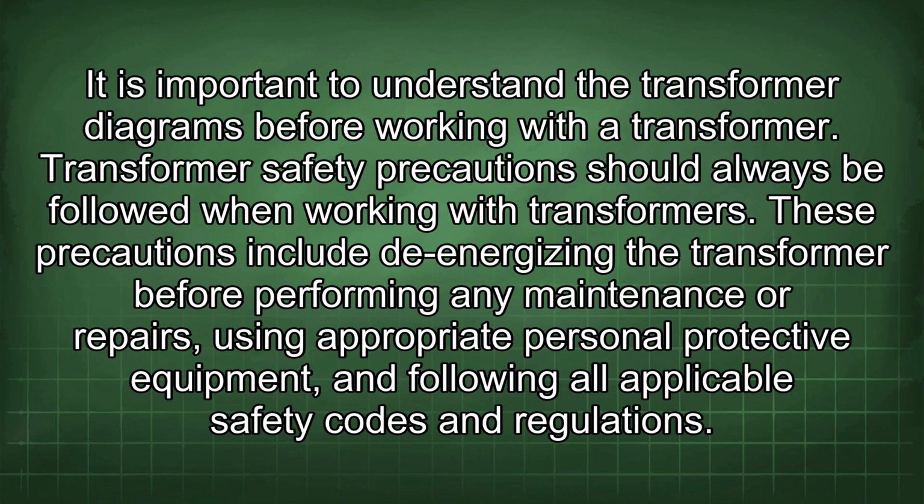Transformer safety precautions should always be followed when working with transformers. These precautions include de-energizing the transformer before performing any maintenance or repairs, using appropriate personal protective equipment, and following all applicable safety codes and regulations.